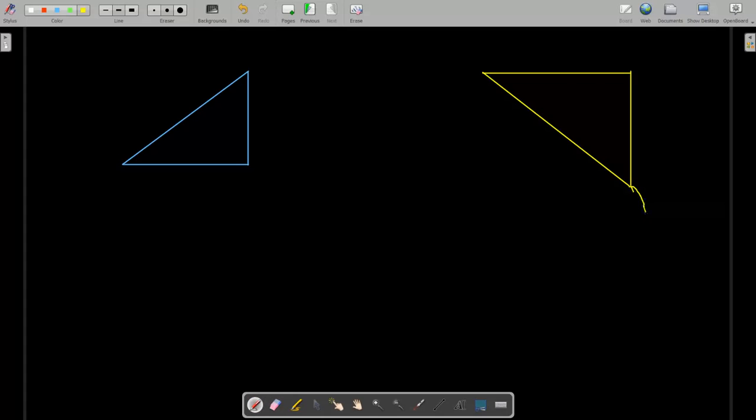Suppose this is a runner blade, so this triangle will come over here. The flow will strike like this, pass through the blade profile and exit like this. This is for your understanding purpose. I am drawing both the triangles separately for easy explanation.